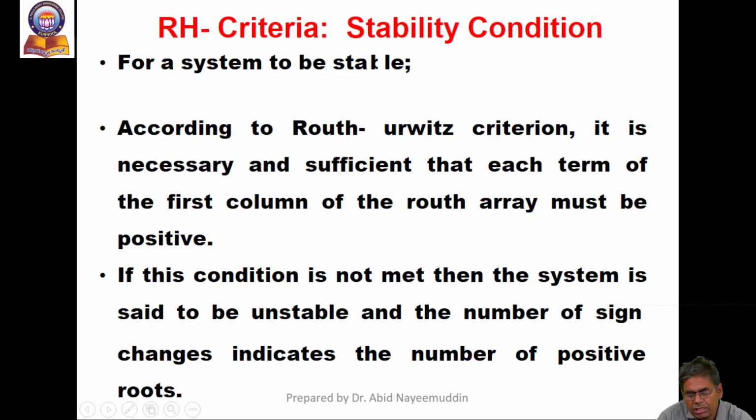Routh stability condition, RH criteria. What is the stability condition? For a system to be stable, according to the Routh-Hurwitz criterion, it is necessary and sufficient that each term of the first column of the Routh tabulation must be positive.